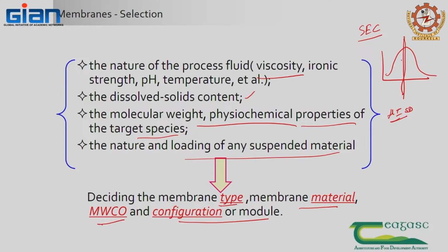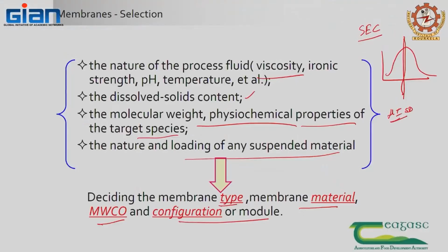A membrane will not do it that way. That is why there could be a difference between a physical membrane system and the chemical way of measuring molecular weight, because in chemistry you get the whole molecular weight distribution, bimodal, unimodal, or drifted, whereas in a membrane you get something completely different. So, it should be within that particular range. These are the ways you can select membranes.